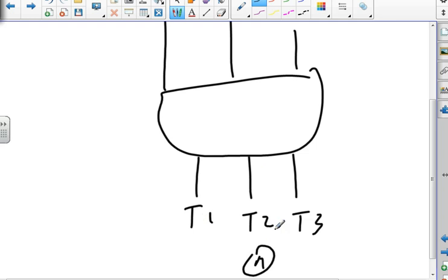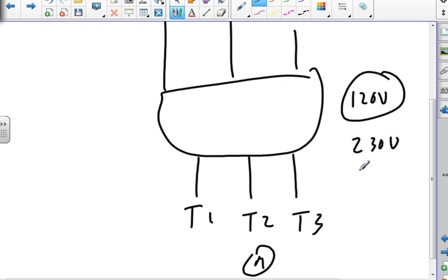Now, the one that we have has a coil in it. It's a 120 volt coil, but you can buy a 230 volt coil or a 480 volt coil and put it in the same thing. Put it in that contactor. So you could disassemble it, take out the coil that's operating at 120 volts. It's about as long as my pen, a little bit wider, and put in a different one. So when those coils burn out, they are replaceable.